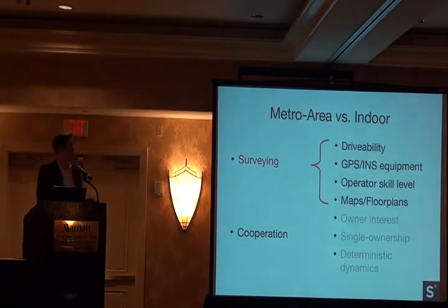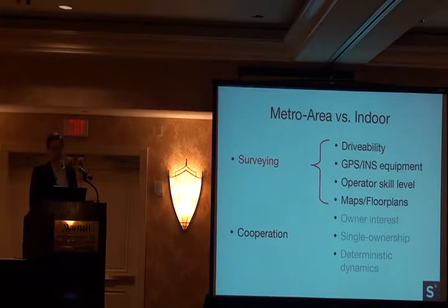So specifically, when it comes to surveying, if we want to do an indoor survey, it's no longer drivable. The venue owners really don't appreciate that. And the kind of equipment that you need to do an indoor survey is also quite different. When we're operating outdoors, we're primarily able to use sort of commodity GPS equipment. But as soon as you go indoors, the GPS availability is spotty, and then you need to have higher end inertial navigation systems or very advanced GPS.